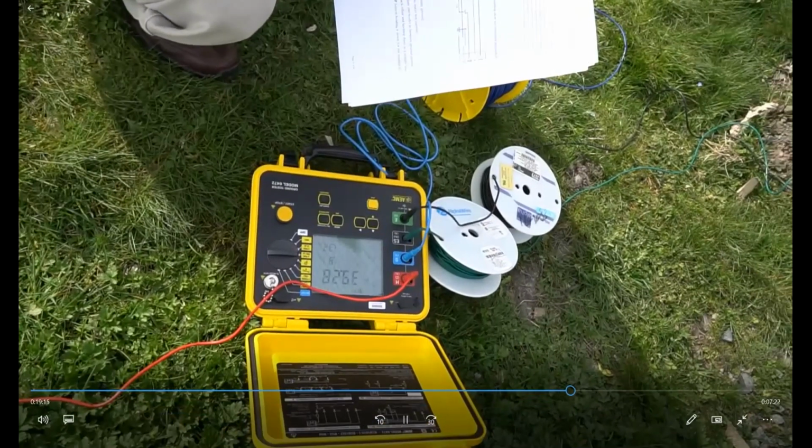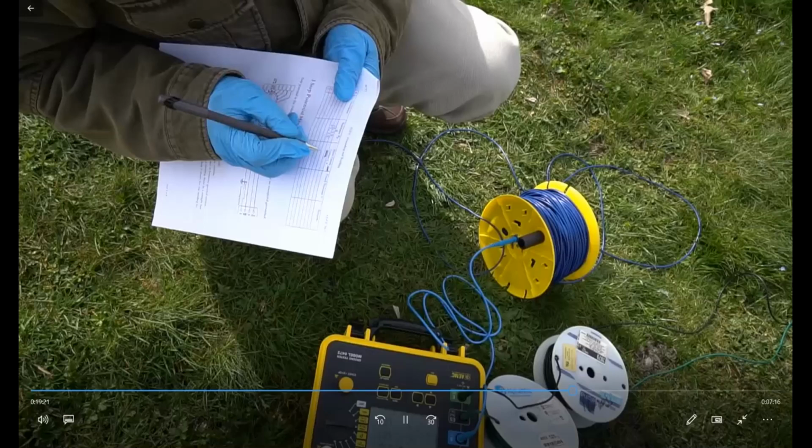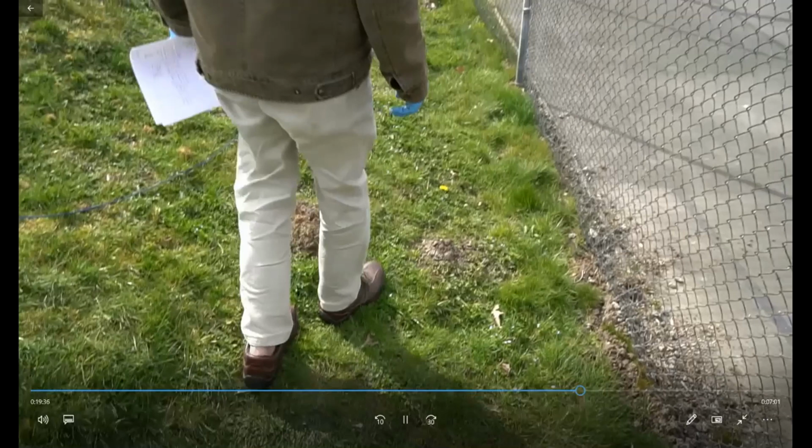and basically we need to find out the resistance. So resistance there is 39.28 ohms. Again, the anticipated amount of short circuit current we will put here and multiply that current value with this resistance value, that will be our touch potential. So this is the second point. We'll take a couple of more points.